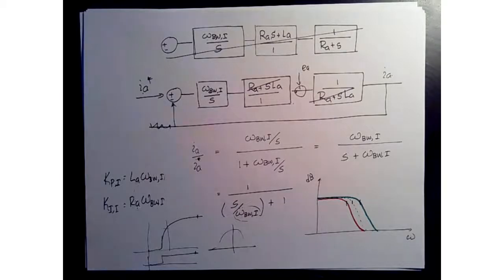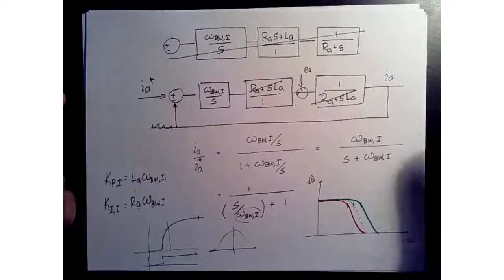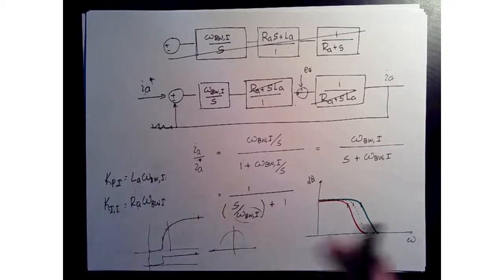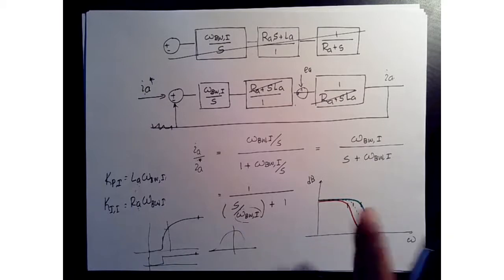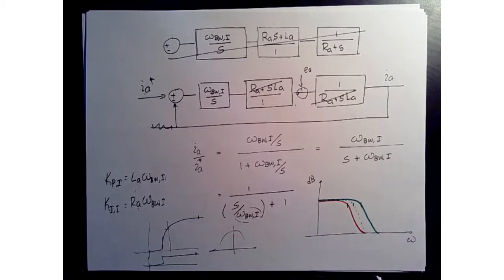It depends on the application, Garrett. If you are looking at a system where you need to focus on accuracy and you need precise actuation, servo, very precise operations or functions, you might want to use the actual resistance and inductance. But if you are okay with some variation, you can use the datasheet value, or the nominal value of the resistance and inductance.